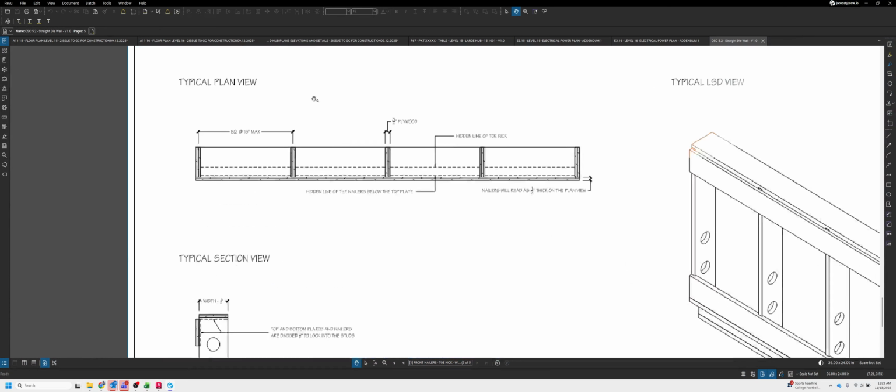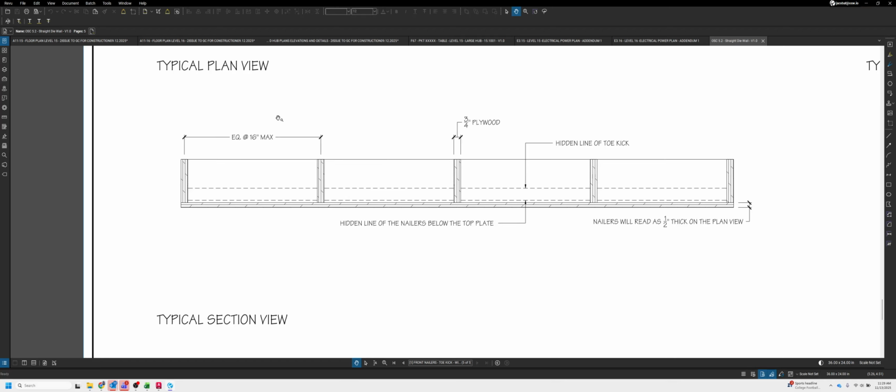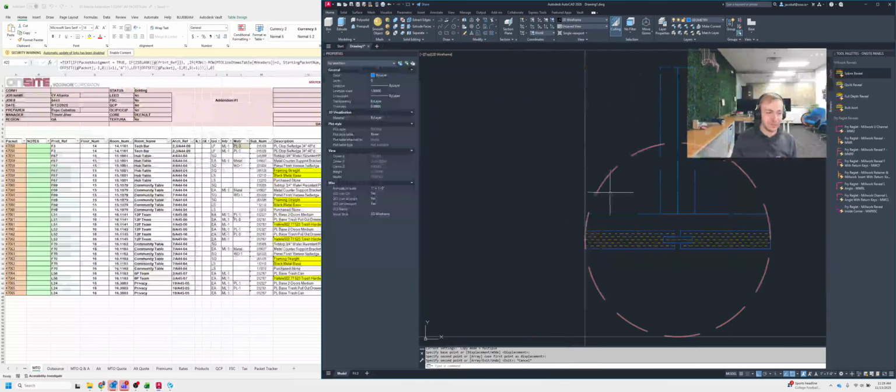And when you're thinking about die walls, the standard really is anytime you have a rib, typically the distance is going to be at 16 inches max. So you don't want to go any more than 16. You are more than welcome to go less than 16 in between ribs. Don't get too carried away though, because you don't want to end up with a wall with like 6 inches between ribs, because that would just be way overkill and eat up a lot of plywood material.